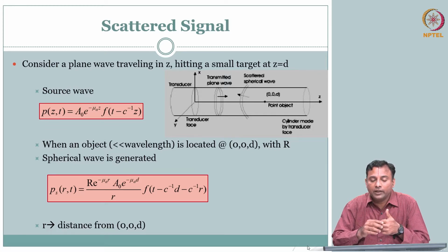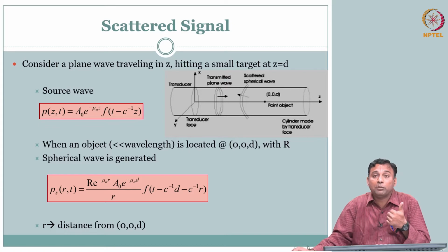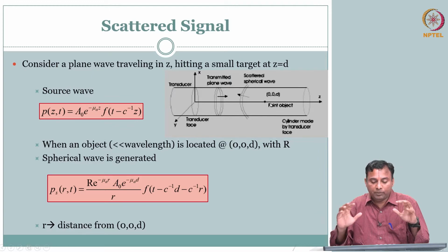So that was one thing, and that was a specular reflection, and then what we called diffuse reflection or scattering, and we ended up having a signal model for the scattered signal. In our case, it is the pressure wave that is reflected from a point which has a reflection coefficient. So this is the part where we identified the physical meaning of the signals that you are going to record and see in an ultrasound image.